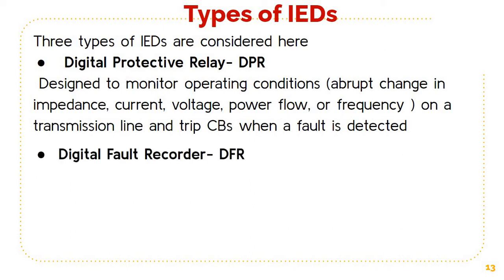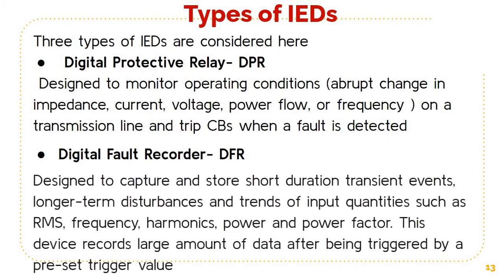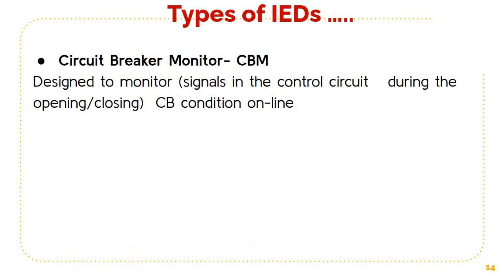Secondly, Digital Fault Recorder or DFR. This is designed to capture short duration transient events, long-term disturbance and trends of input quantities such as RMS frequency, harmonics, power and power factor. So this DFR records a large number of data after being triggered by a preset trigger value.